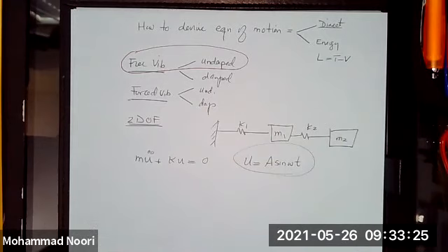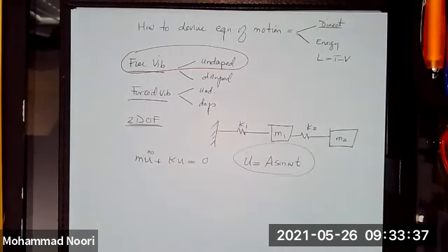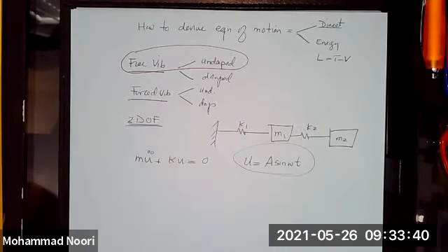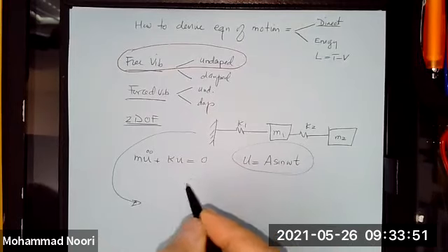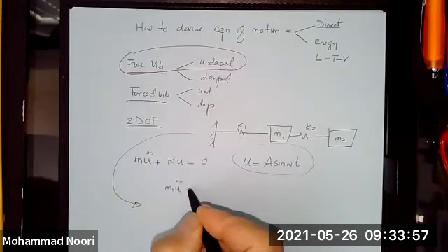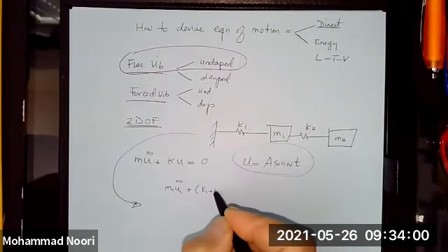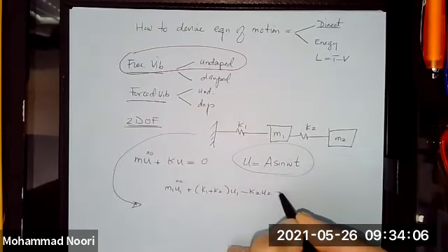And you would basically substitute this back into the equation. You found the frequency, which was a natural frequency, and we solved for the two roots and so on. So we do exactly the same thing here. Since we have the equation of motion for this case would be of this form, M1. If you set up the equation of motion, this is what you have: K1 plus K2 times U1 minus K2 U2 is equal to 0.